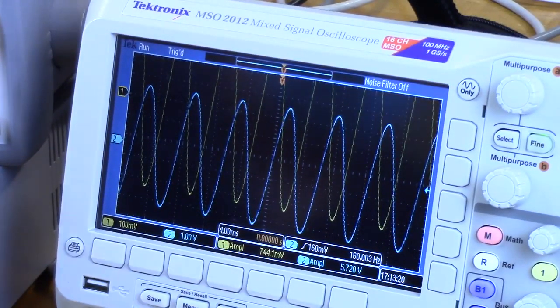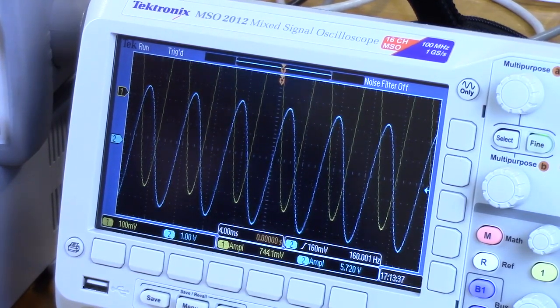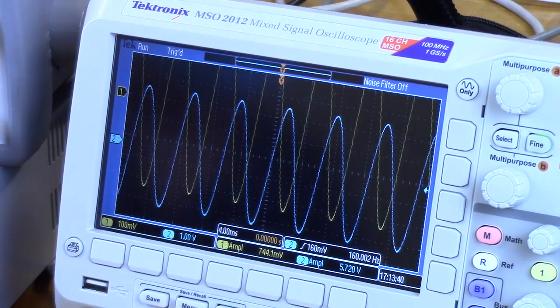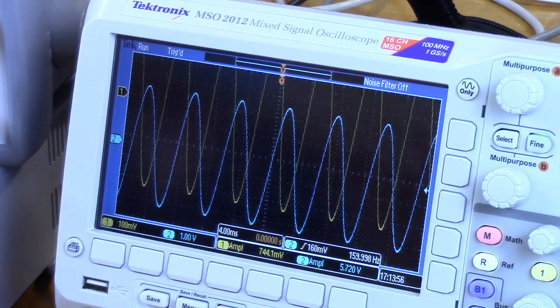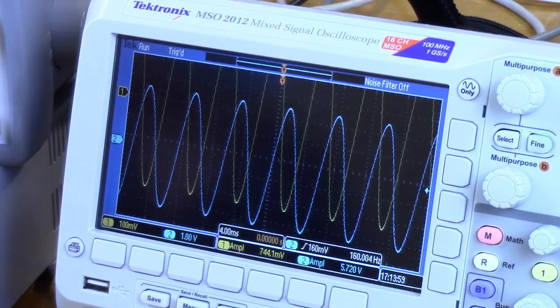The only thing left is to measure the value of R2 with the ohm meter, which we still haven't done. So this completes all the measurements. There was a lot of shenanigans going on with the oscilloscope. Oscilloscopes do not like looking at slow waves. We had to resort to external triggering because these waves were not only slow, but small, and we had to do a lot of playing with the oscilloscope to get these waveforms to show up. Even so, I'm not convinced that these are totally reliable measurements, so you're probably going to see some pretty large statistical errors. Don't take it personally. It's a very imprecise way of measuring these things.